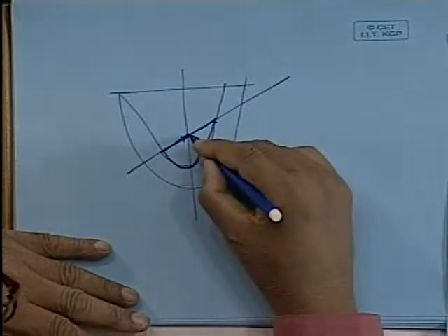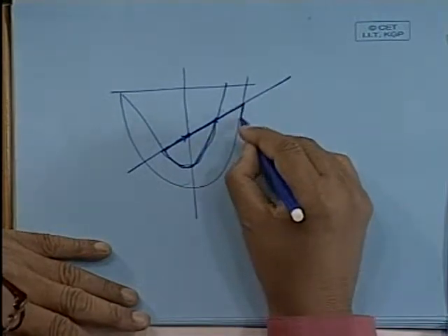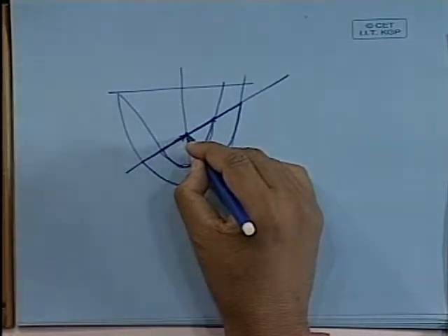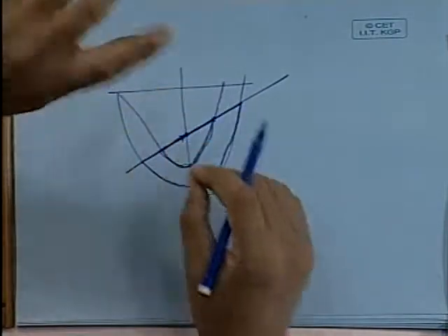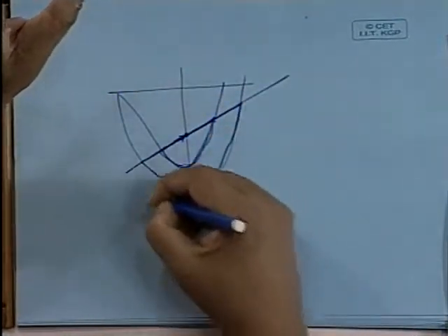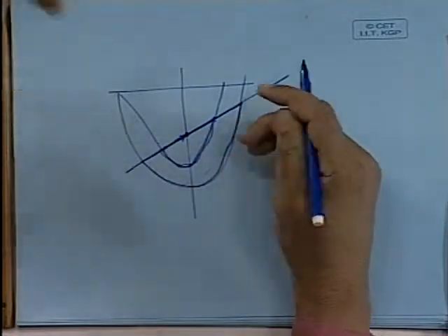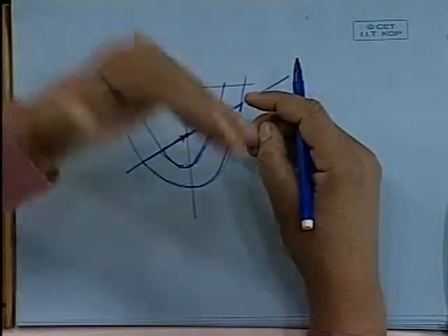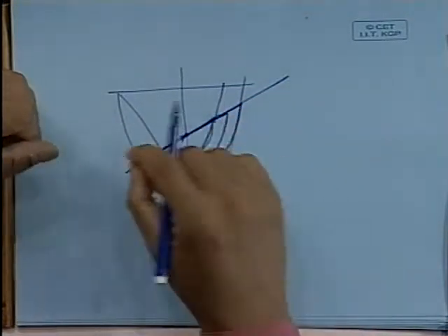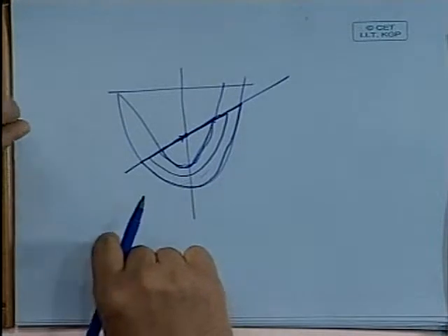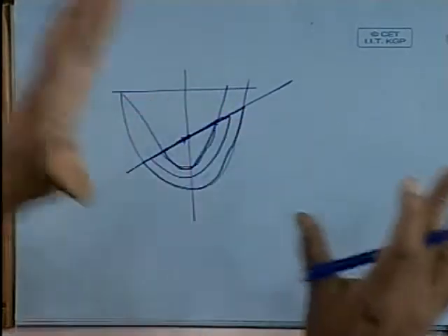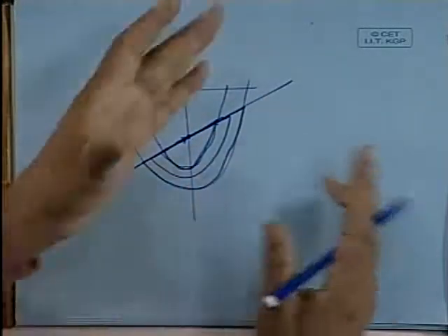Now again you start from the next one from here, go up to this, come back here and come to this point. So you got the area of the next one. That got added because the first area is already stored. It has rotated so much, say some reading is there. Now this is getting added on that. So it is adding it to the cumulative, exactly. It is cumulative. Therefore, in the next one you again go to the next station. So what happened? If you go carefully, you see the entire exercise reduces just to one set of going through the entire station. You will directly get the volume and also the moment.